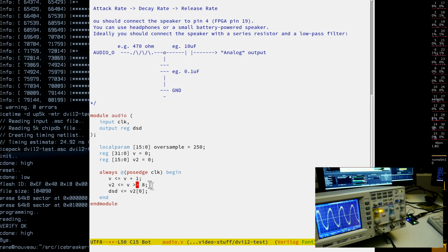As a short test, for example, dividing this further by 8, so counting this down just for a test to show you the signals. This is basically dividing this further by 8. Although you always need to take into account that because when we count and use the last bit, it is already divided by 2, because we alternate between 0 and 1. So 0, 1, 2, or 3, and so on.